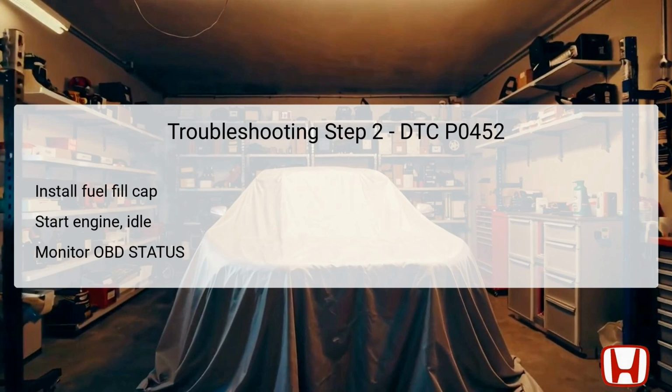This monitoring will help you understand if the error is persistent, indicating a confirmed fault, or if the system regards it as intermittent. Should the HDS indicate that the DTC has failed again, you will move to the next step for deeper investigation. If the status shows that the DTC has passed, the issue may be transient, and further checks for loose connections may be warranted.